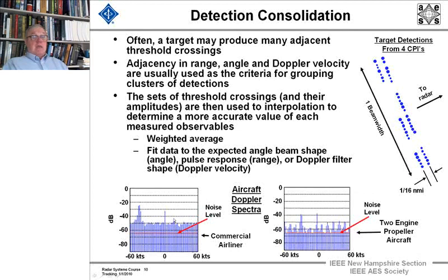And you know a commercial airliner has fans on their jet engines that go around at very high PRF, extremely high frequencies. And what we're seeing here is just plus or minus 60 knots. We sent the pulses out at approximately 1 kilohertz. And we see here a bump where we get the main signature of the target.